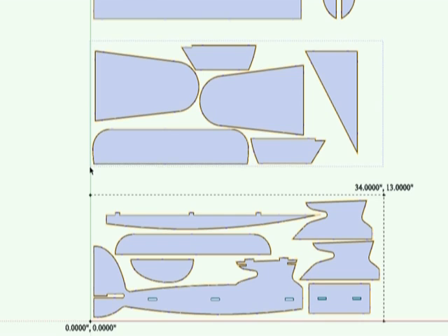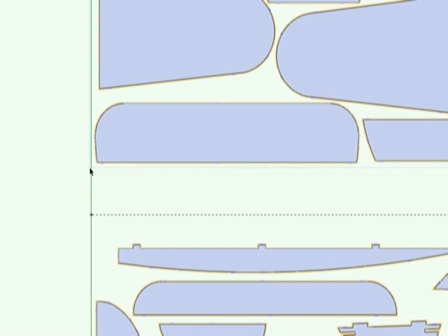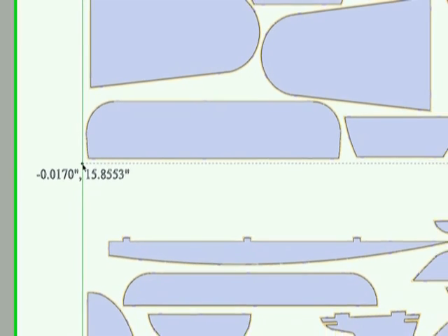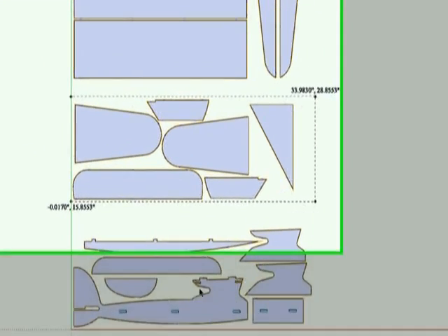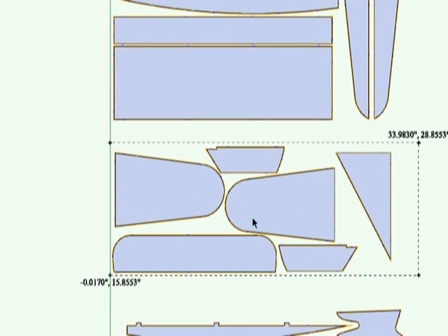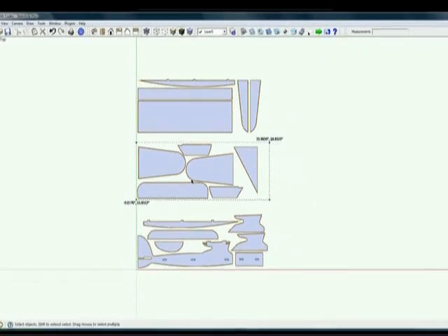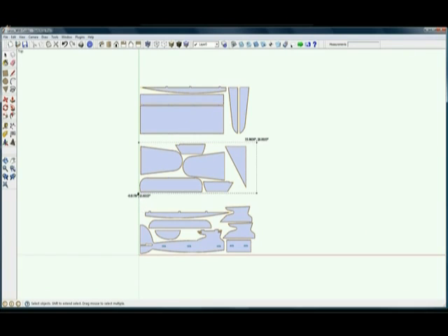And if I bring this over into position for the sheet, put it wherever I want to, and that looks pretty good, and I click, well, now it's moved our box from this 0, 0 position up to this next position. And now I could generate my flat code for, say, sheet 2 without having to move any parts. Remember, our bounding box will only allow gCode, flat code, to be generated for the parts within this box.